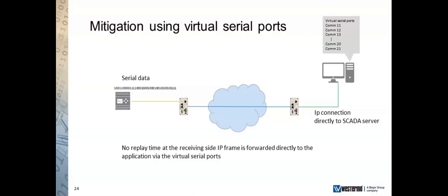But if you've got 20, 30, 40 comms ports that you want to physically replace, and then make virtualized, that will quite happily fit into a normal server footprint, and you will be able to get all your virtualization up into the SCADA server itself. Why is that an advantage to you?